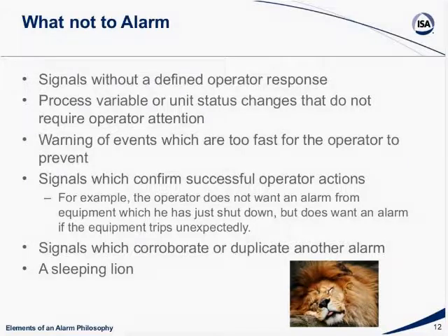But what don't we alarm, okay? Well, and this is something you'll find a lot. There's a lot of alarms that are configured in the system, but there's no response required from them from the operator. And as you go through the rationalization process, those things just get moved away. Unit status changes, for example, that do not require operator attention. I don't know how many times I've seen at facilities where a pump gets turned off. The pump is supposed to be off now, but they end up getting a low flow alarm. Well, you're supposed to have low flow. You're supposed to have no flow. The pump is off. And so these are things you want to make sure you do not alarm, things that don't require an operator action, okay?